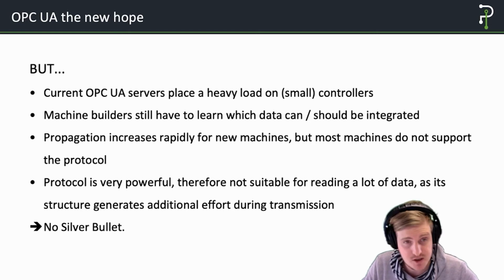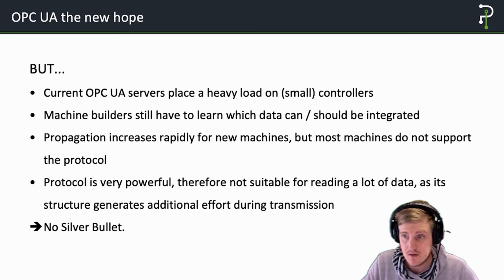It supports things like encryption on the wire, subscription-based protocols, signing of messages. But the drawback is it adds overhead, which can sometimes be an issue. If frequency or sampling times get really high, that's an issue because it takes away CPU power from the PLC.